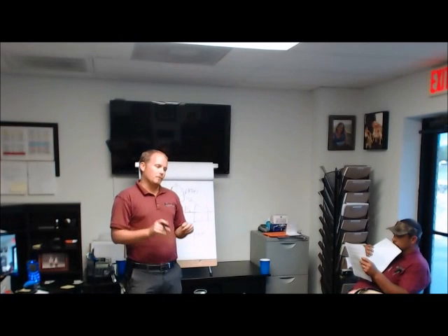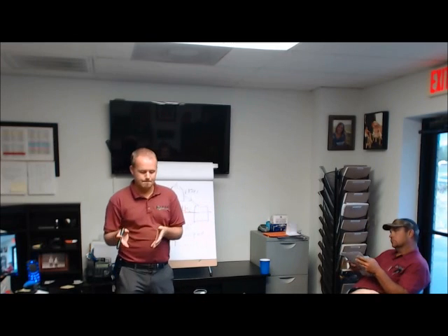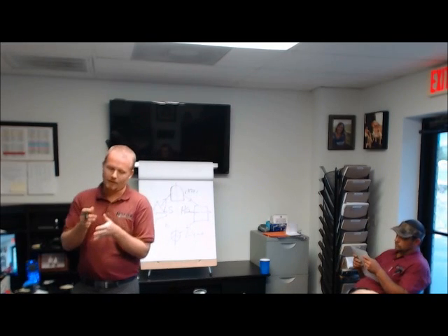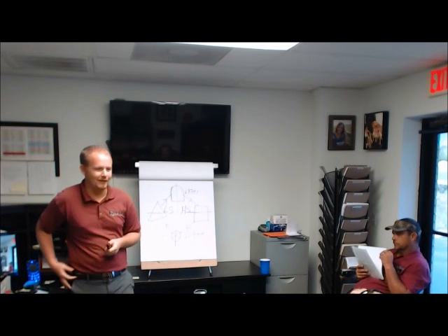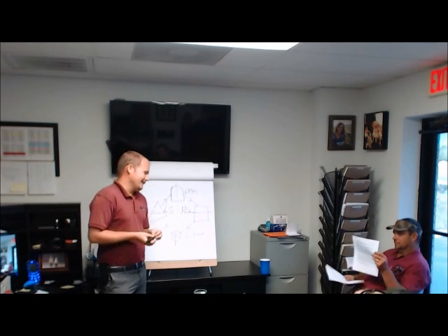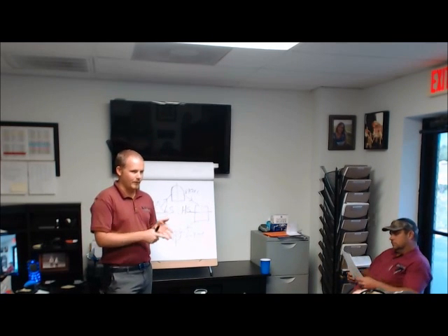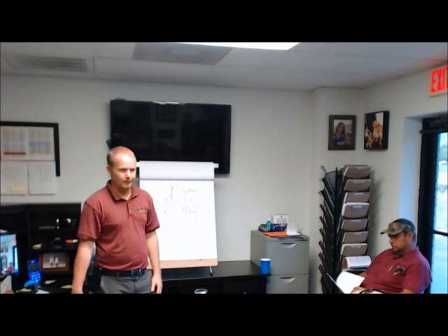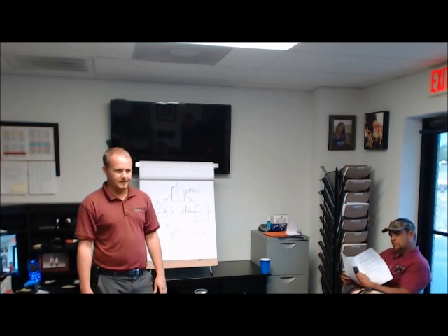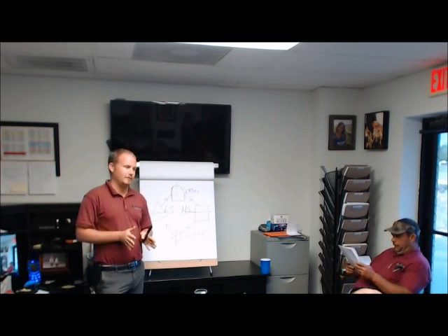Okay, so now we're going to talk about checking and setting refrigerant charges. I talk about the 5 pillars. I came up with that before I knew anything about the real 5 pillars. So you have suction pressure, head pressure, subcool, superheat, and air temperature split. We're talking generally about our regular day in and day out residential systems. This is nothing complex. We're not talking about chillers here and water splits and stuff like that. It's standard basic stuff.